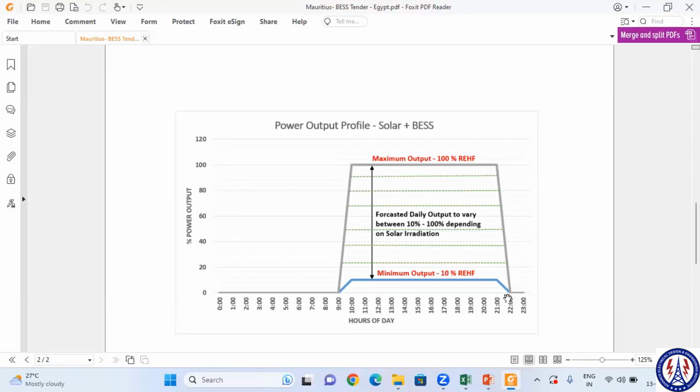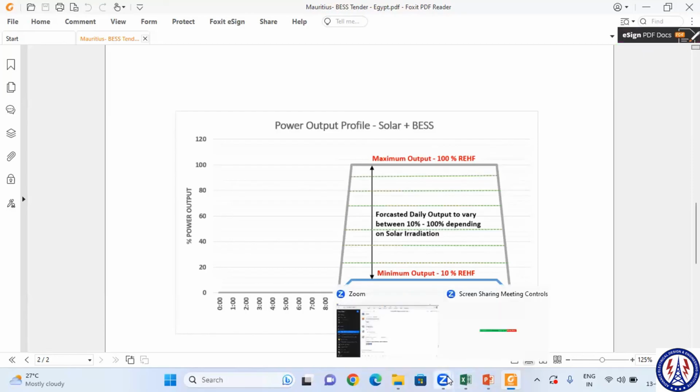And for generating 25 megawatt hour, with DC side 12 megawatt, how much would your generation be for a day? Considering 4.5 or 5 units for one day: for a 1 megawatt plant, it's 5,000 units per day, correct?